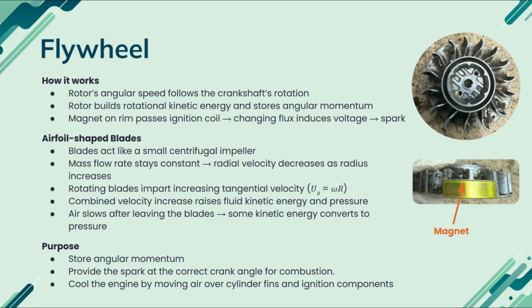moves outward. The extra kinetic energy and the associated rise in pressure comes from the work the engine puts into spinning the flywheel. All of this produces the outward cooling airflow that moves across the cylinder fins and the ignition components, carrying heat away from the engine.